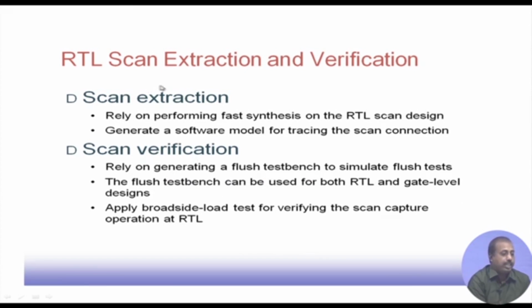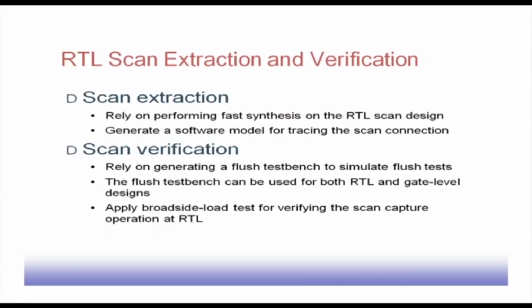Scan extraction and verification. So, scan extraction will rely on performing a fast synthesis on the RTL scan design and generate a software model for tracing the scan connection. So, again the same thing, it is trying to work at the RTL description level itself. It will try to see where the scan lines or scan chains are inserted. So, it is actually the lines that have been inserted into the description. Corresponding to that, what will be the circuit that is synthesized.